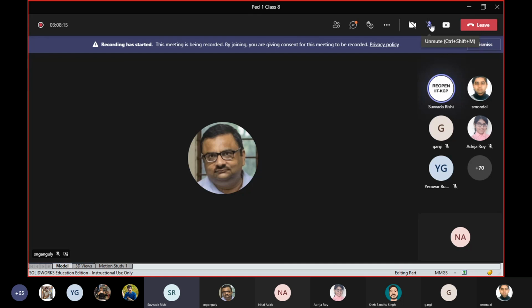But when I did the iterations, the Reynolds numbers in both cases kept decreasing. When I got the relative error below 5%, the Re went to 5K on the tube side and 7K on the shell side. Will that be fine, or do we have to do something else?